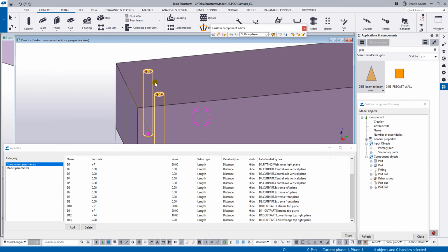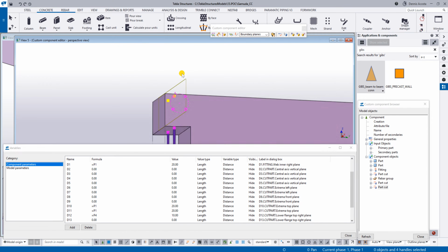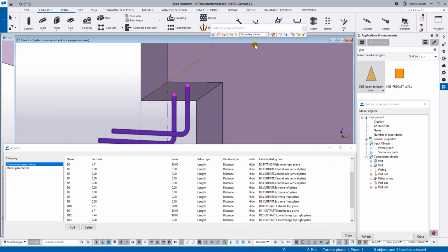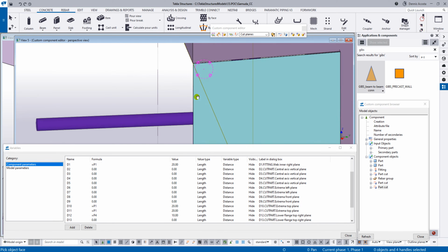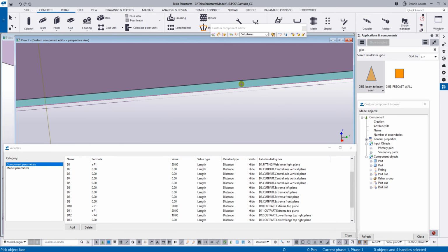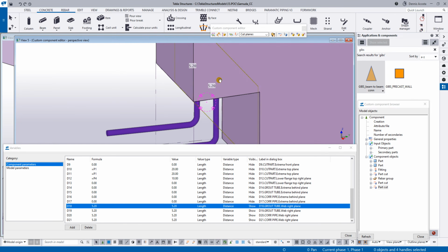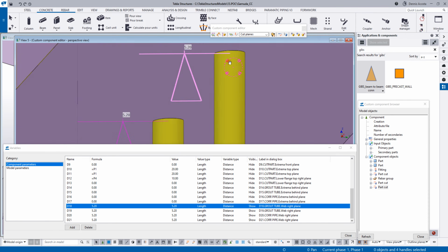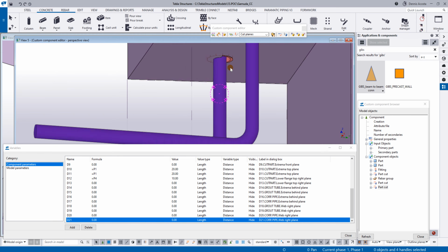Okay, I can just simply select by window, and then the first thing is I'm going to Alt key, and then bind that one to the boundary, this one, and the bottom, I'm going to bind that one to the cut. So bind to cut. Oh, the thing is I cannot, here. Yeah, this one, see? I can bind it here. This is the cut. Okay, that one is 520. Why is it 520? I think I need to put this one 0, and then hide. Okay, so that one is bound to the cut.